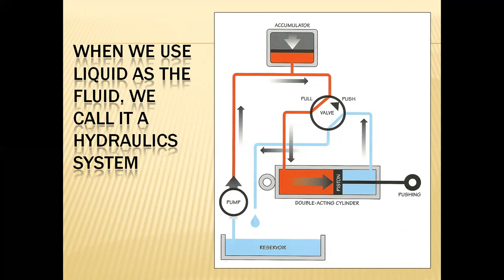This is the movement that we have seen in the previous slide: when the pump or pressurized fluid enters, it directs towards the forward movement while the fluid enters input port 1, and port 2 will return the fluid back towards the reservoir, and vice versa. If the fluid enters the other channel, a retraction stroke will be commenced, and the pump will be connected to piston port number 2, and port 1 will be drained back to the oil reservoir.